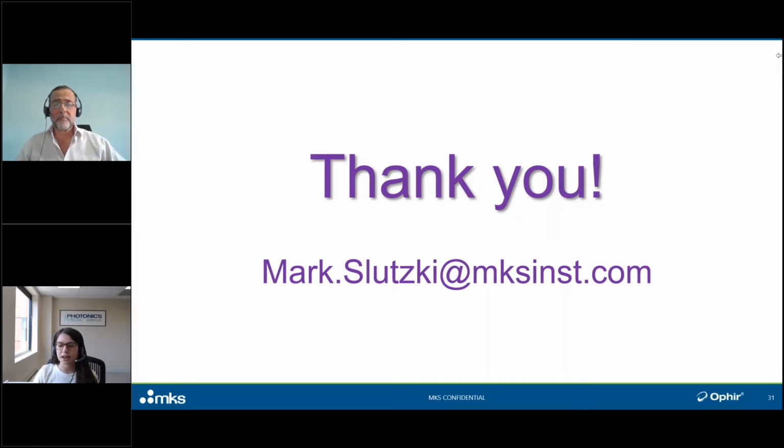Thank you. This next one asks, can cooling vents or chambers be used to reduce heat zone? That's an interesting one. My first thought would be that I doubt it because we're talking about small heat zones that result from pulses that are lasting maybe some nanoseconds or microseconds, and during those few nanoseconds or microseconds, the heat's propagating through the material. So we're probably talking about a heat affected zone that's not a few millimeters in size, but probably more like micrometers. So I doubt that environmental temperature would really have much of an effect.